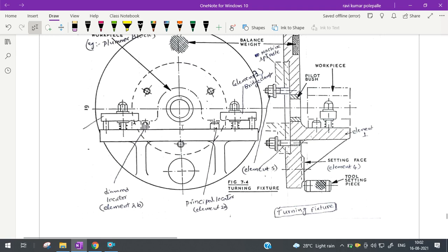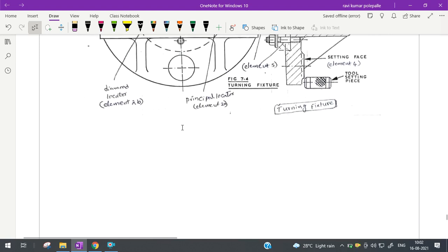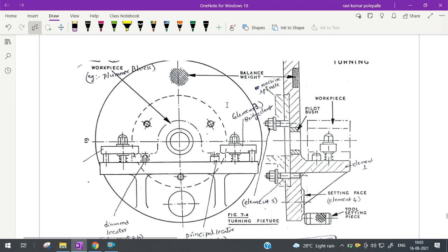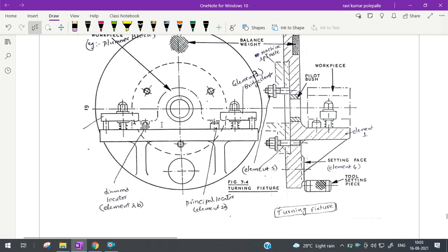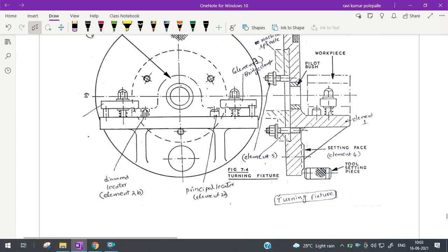Of course, we should talk about the quick acting nut also. What is this quick acting nut? This quick acting nut is a type of quick acting clamp. How does it act quick? We have to look at the construction. Only then we can tell how it works. Unlike the normal hole, inside this nut it shall have an inclined hole through which the workpiece passes, or rather we push this when we want to operate it.